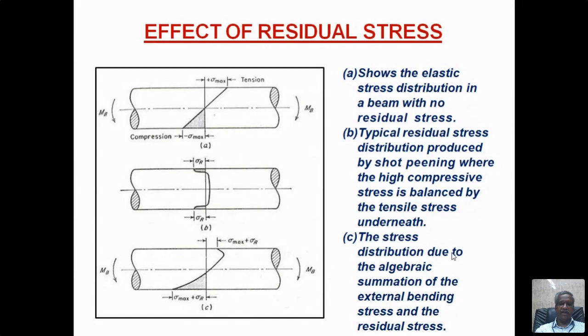And there are many methods available for surface rolling, shot peening, polishing, thermal stresses. They all introduce compressive stresses. Compressive stresses, as I told, will close the crack, partially close the crack. That's why I explained that in the case of crack initiation itself, it will crack, and the crack growth itself, it will close partially. So it will decelerate the crack growth. So that's why it is beneficial.